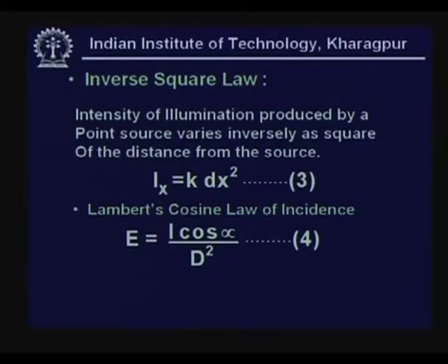The first law says that the ratio of luminous intensity to the perceptible change in the luminous intensity is a constant, and this sensation with respect to the human eyes is logarithmic in nature. That is a very important issue. So, you cannot keep on increasing the illuminance, light output, luminous flux, and yet expect your eyes to get better and better. Since it is logarithmic, the marginal increase may be enough. Beyond that, unless you try to have more uniform flux gradient, you cannot get any improvement in the observational characteristics.